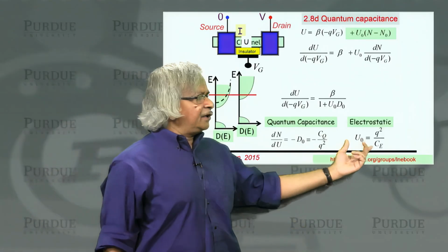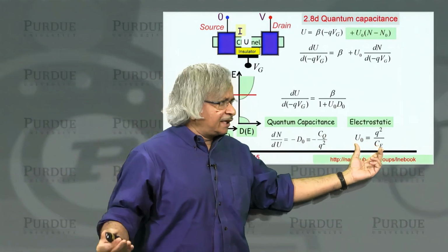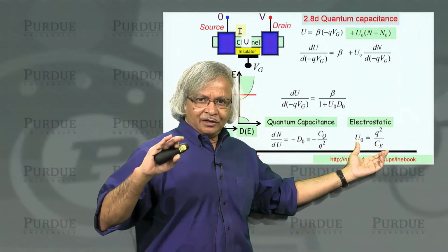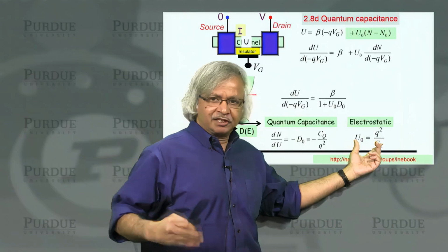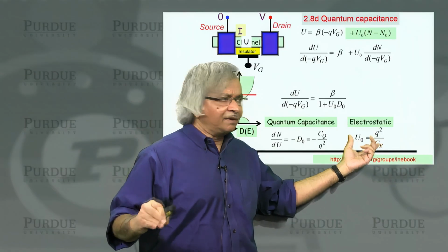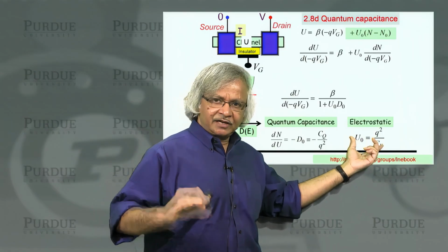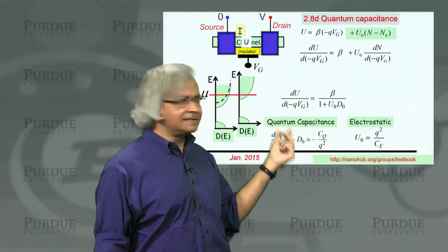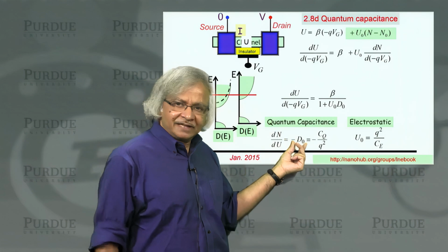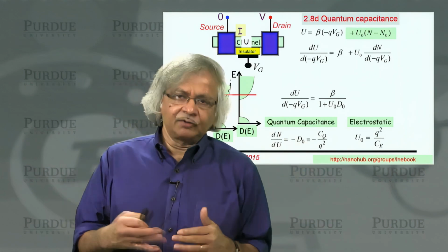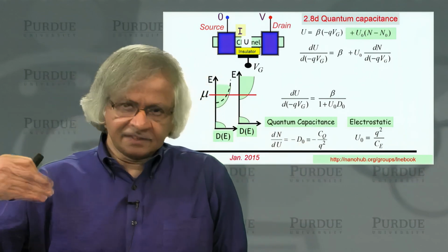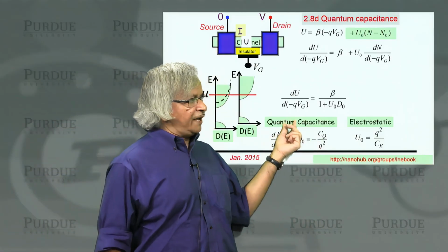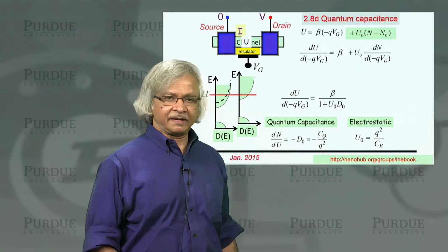And you could say, well, this in a way is just electrostatic interaction, which is this 19th century physics. Although nowadays people have corrections to it, which is based on quantum theory. But basically it is this electrostatic interaction. By contrast, this one, the reason you call it quantum capacitance is that it depends on density of states. And density of states requires wave nature of electrons. And the starting point is like Schrodinger equation, for example. So that's why the two names, this quantum capacitance and electrostatic capacitance.